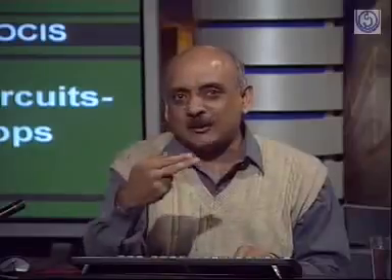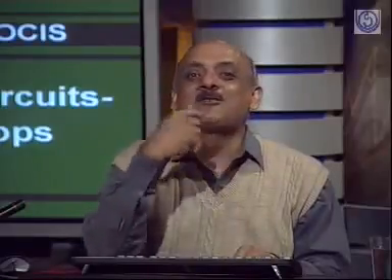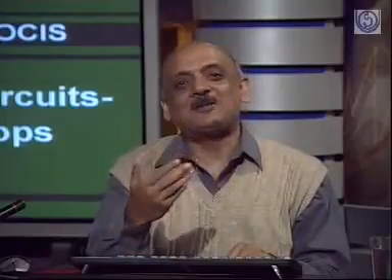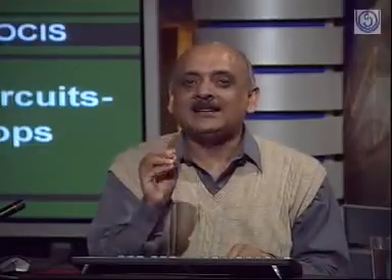You must know that the traffic light changes after a particular specific period of time, right? So you require a circuit to do that particular activity, and a device or a circuit which stores that particular element, that is, what the current state is. So wherever you require a typical sequence, you require a sequential circuit. That's what the name is, the sequential circuit. You move from sequence to sequential circuits. And what do you require? Once again, just the combinational circuit and the storage element.